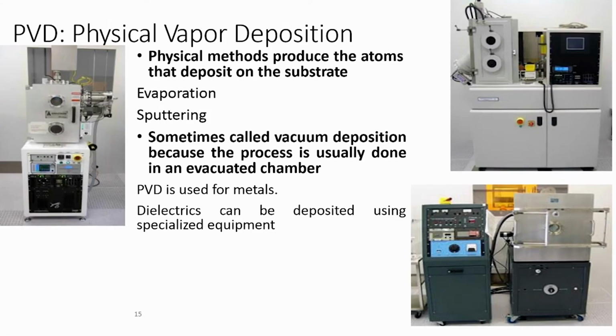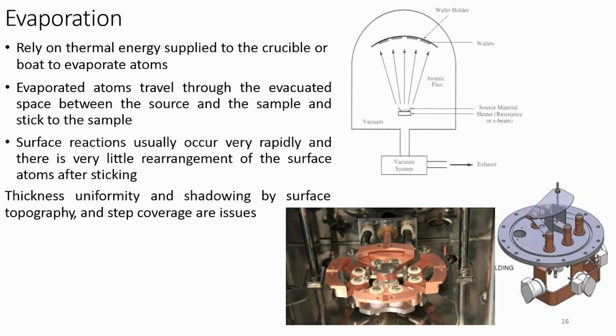Now, let us go to your first technique, which is a physical vapor deposition technique. I have explained to you in earlier classes how thermal evaporation works. Let us in this class see the video of thermal evaporation. As we have seen earlier, these are the substrate and source holders, and when you load a source between one of the source holders, let us say between this and this, what will happen? When I heat it, it will evaporate. This is exactly what is shown here.